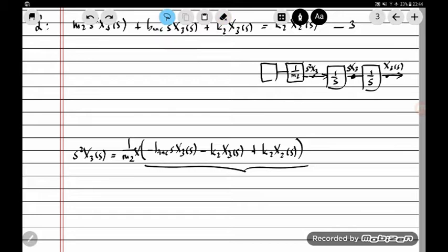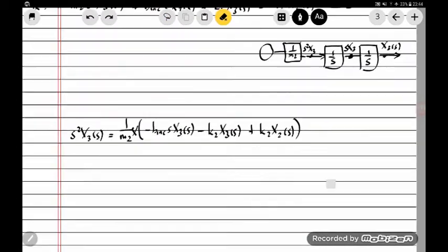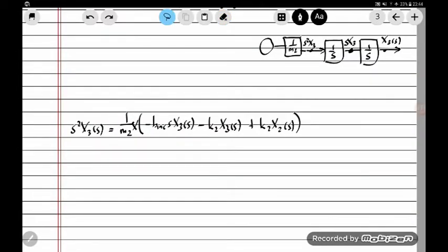Remember, multiplication is just two transfer functions in series, so that's why you can draw them in series. But remember, this is a sum of signals, so to represent a sum we use a summation block, so we can modify the diagram like that. So that's a summing junction. Now looking at this summing term, we can read off and see what needs to be summed into that summing junction.